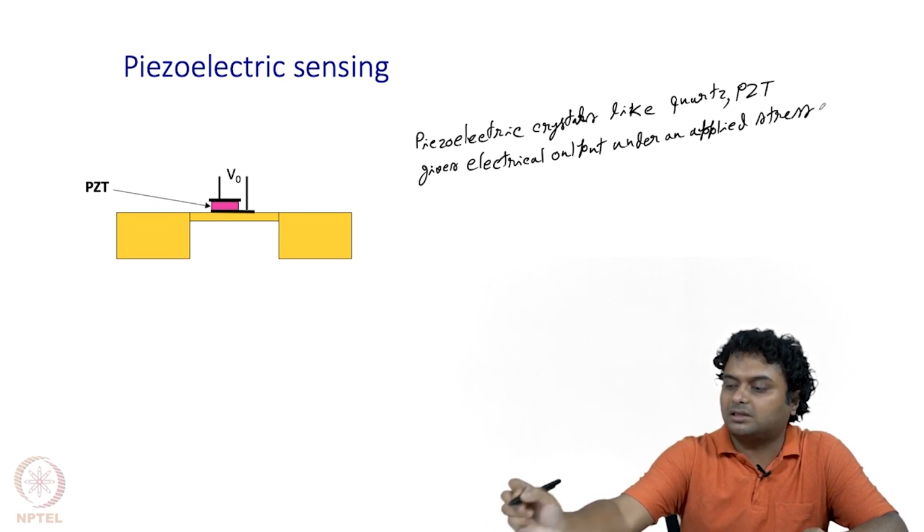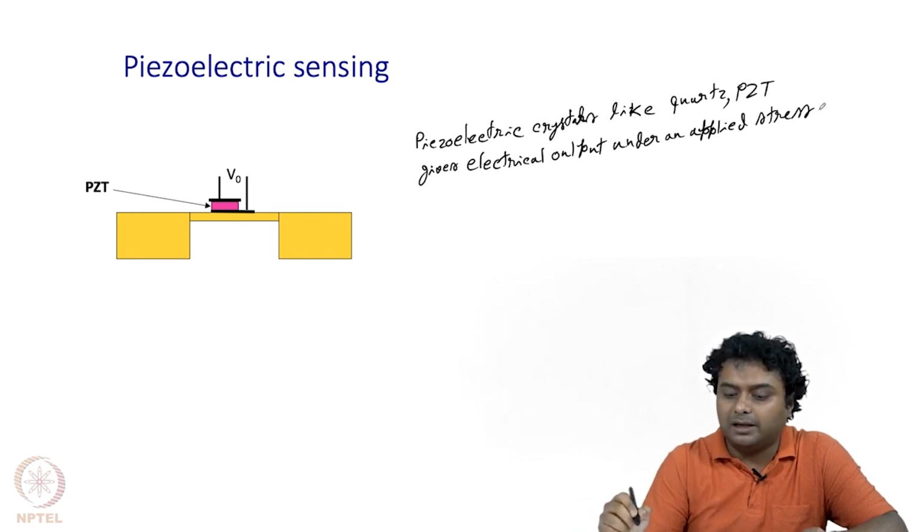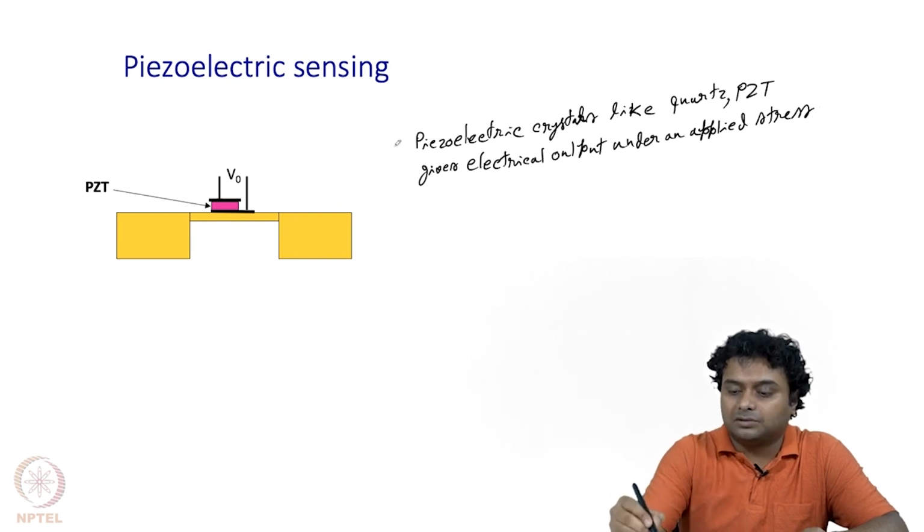And why is this stress coming? Because the pressure is making the membrane deflect or bend, and because of that, stress will be applied on the piezoelectric element. So, this is one point.